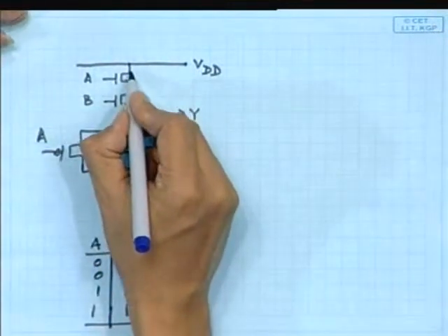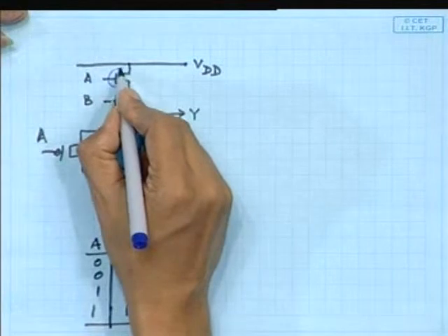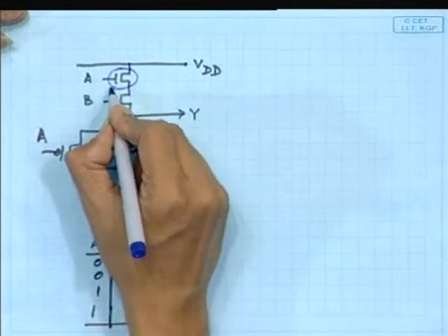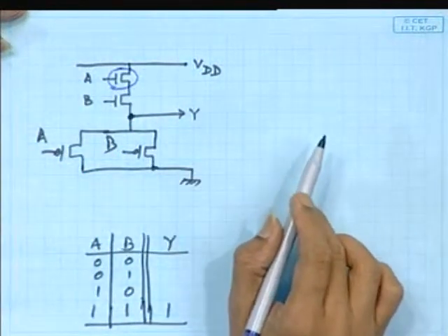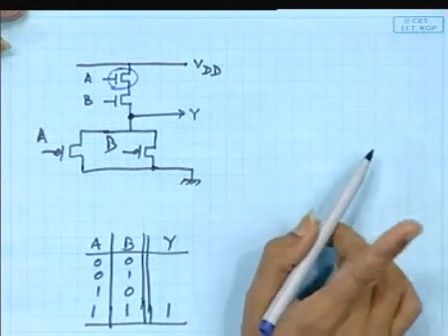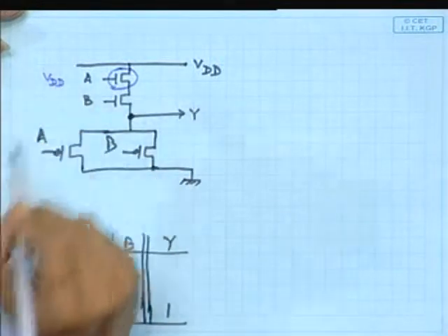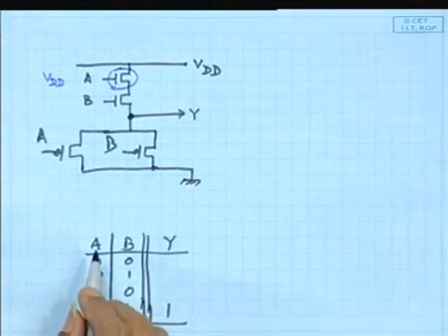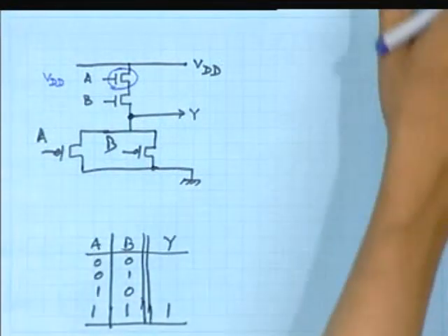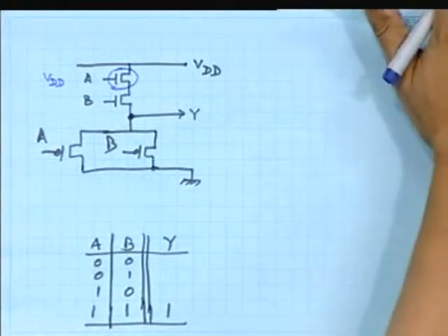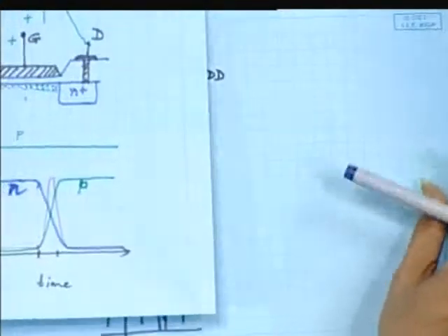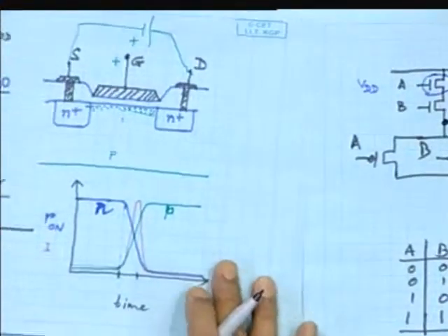This is something like an N type transistor, right. An N type transistor will be able to work when its gate is at a higher potential. So, higher means what potential? That is at VDD. So, if you look at the structure that we have seen for a MOS transistor, it is something like this.